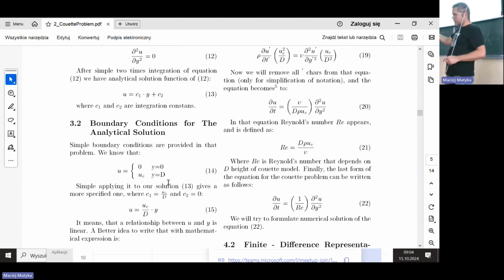So the higher velocity means higher Reynolds number, yeah? Larger systems means higher Reynolds number, and so on. And now, why is this so important? This is important because if we didn't have the Reynolds number, we would not be able to do experiments in many situations. What people do, they can, because the physics is the same, independent of scale. I mean, of course, in some range of scales.